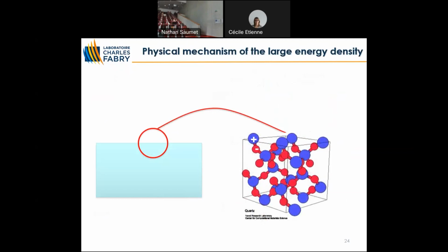So the silicon has lost partially its electrons, so it has a positive charge. And of course you have a vibration frequency of this link, this covalent binding. When you have the oscillation here, it oscillates at a particular frequency. And since the atoms are carrying charge, that's a dipole. So now I have a dipole, which is close to the interface and which is oscillating at a well-defined frequency.